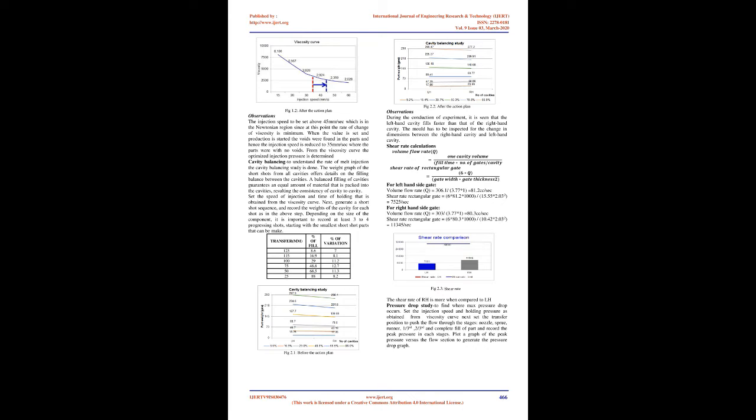Fig 1. CFT Outer. Viscosity curve. To check the injection speed setting in the Newtonian range, set the holding pressure to 0, make a short shot that fills 95% and note the fill time and peak injection pressure. Now lower the injection speed to 90%, 80% and so on, and note the fill time and peak injection pressure. Obtain the intensification ratio of the screw from the machine manufacturer.